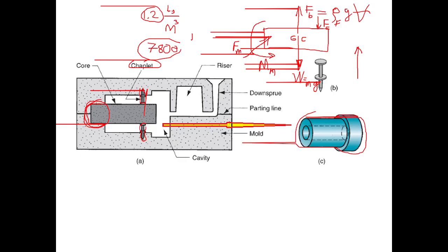Such a study is included in the content of this course. But the rest: after finding the force applied by the chaplet, then find the surface pressure. Surface pressure is the pressure at this contact surface. Well, the area of the tip of the chaplet is the contact area at the denominator, and the force exerted by the chaplet is the numerator.